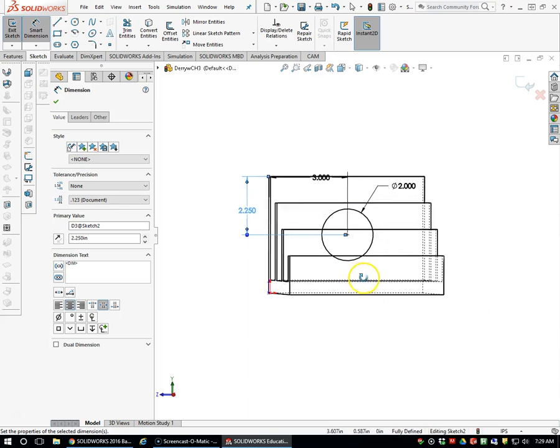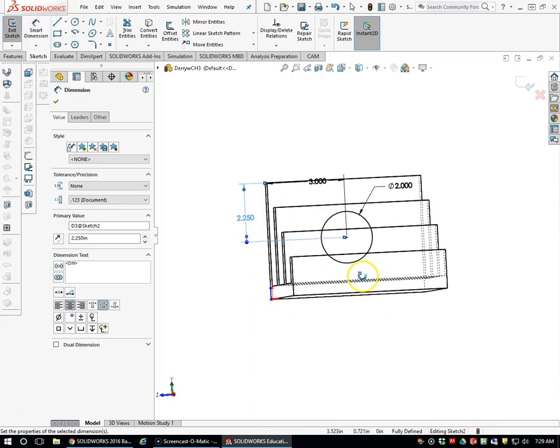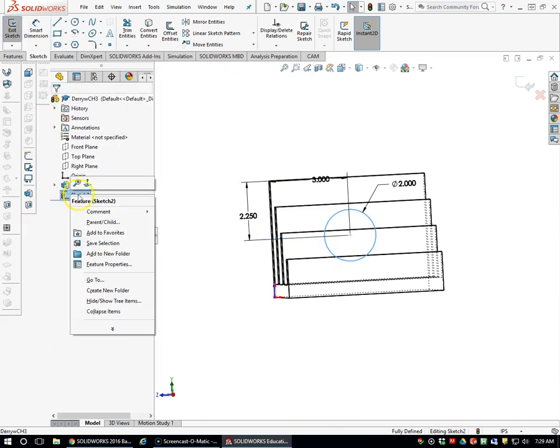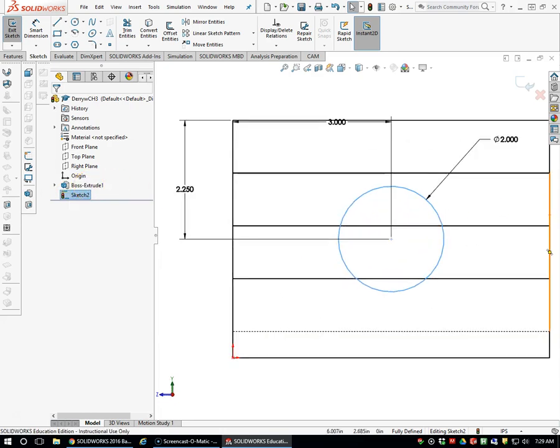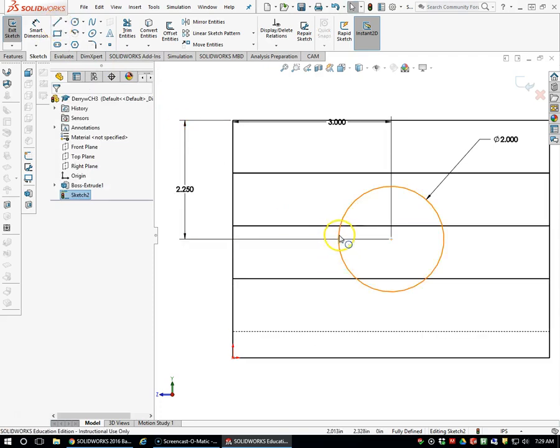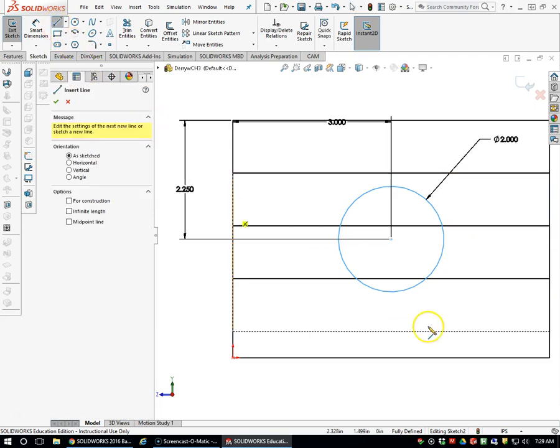If we were only drawing a circle there, we'd be all set, but we're going to add some more to this. So I'm going to click out of the dimension. I'm going to bring myself normal to again, and we're going to draw some vertical lines, and we're going to have those lines snap to the quadrant point. So I'll show you what that means. If I take my line tool and I hover over the 9 o'clock position on my circle, if this were 12 noon and 3 o'clock and 6 o'clock, you'll notice that I can snap right to that spot.